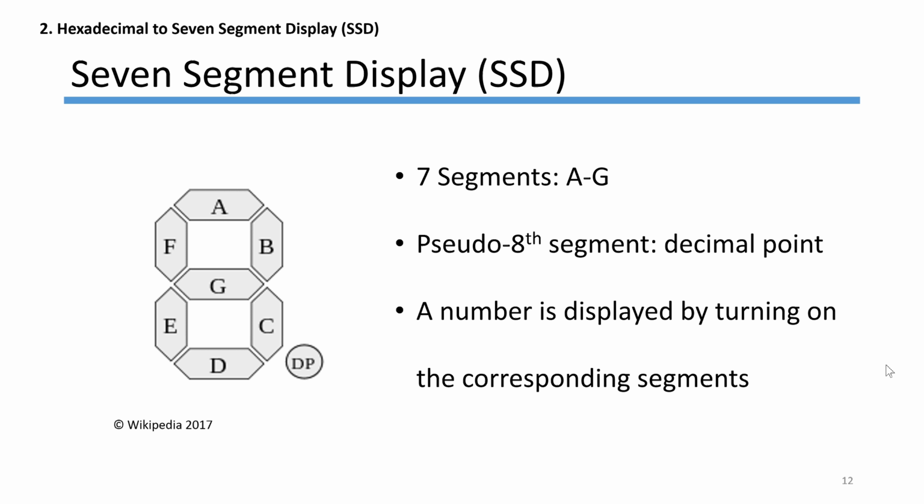On your MXK boards, there are 6 7-segment displays. These are LEDs, which can display a number or a letter. As you can see in the image, there are 7 segments to display the number or letter: A, B, C, D, E, F, G. And in our specific model, there is an 8th segment called decimal point, as you can see as DP.